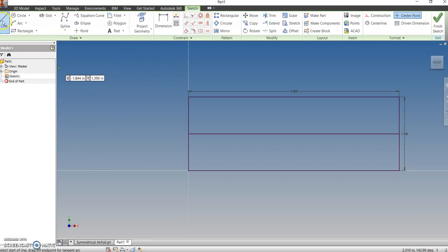All right. Initially, I'm going to use my line tool, and with the particular design that I have, an arc going in the front, I'm going to make a guideline first that's about 1 inch back from that top left-hand corner. And I'm going to go to my arc tool now. I'm going to select this midpoint and then click on this other point that I just created, and bend that around, again staying within those parameters.